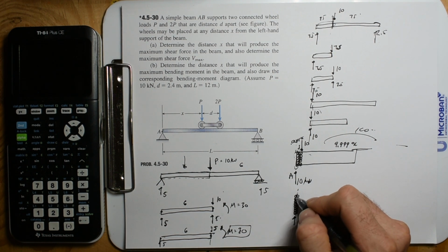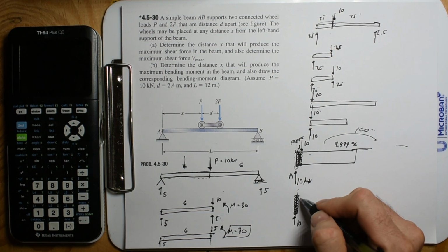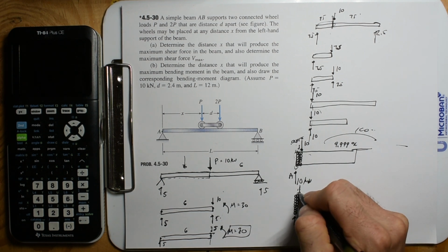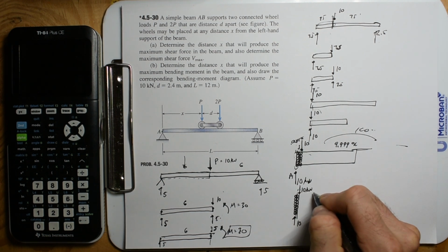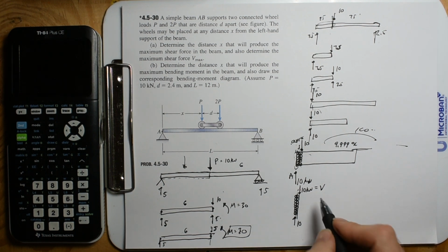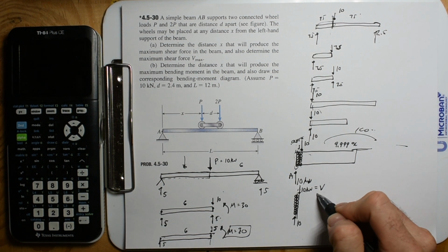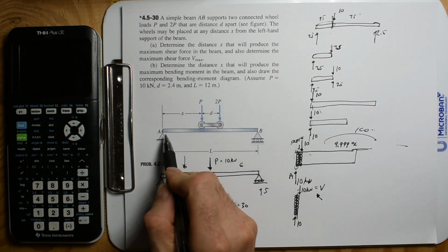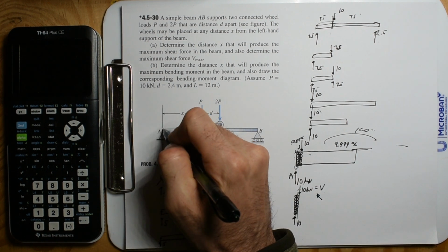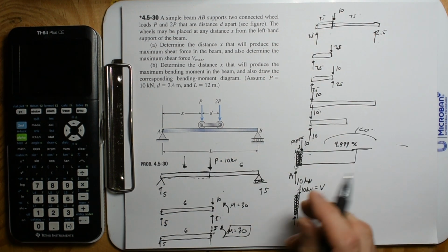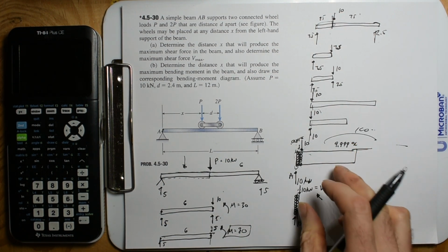But this isn't balanced, and the only place that we can generate a force is on this cut surface. So we're going to have a 10 kilonewton force down, and that is a shear force. You know what I mean? So that is the shear force. So the biggest shear force you can generate is when this load is as close to A as possible, but just a molecule away, because you're trying to shear molecules away. That's the only reason this